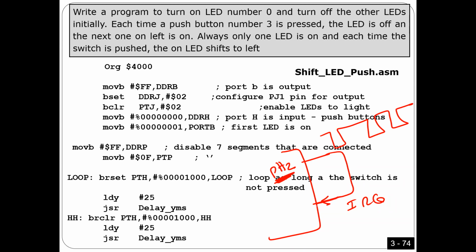When I connect a wire this way, the signal is going to come to here. When it comes to here, every time there is a falling edge, you trigger an interrupt. So based on my understanding of your question, I didn't tell IRQ to take the signal from somewhere; I didn't write code to do that. The wire is going to connect.